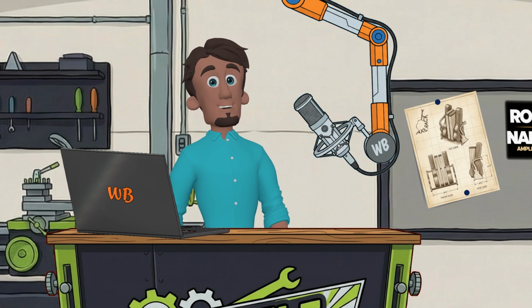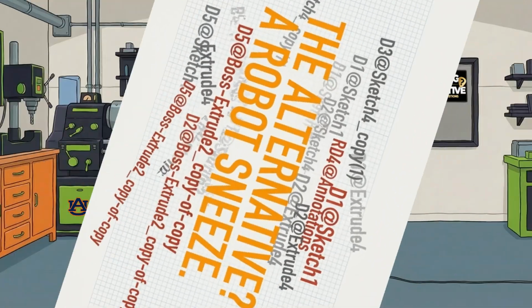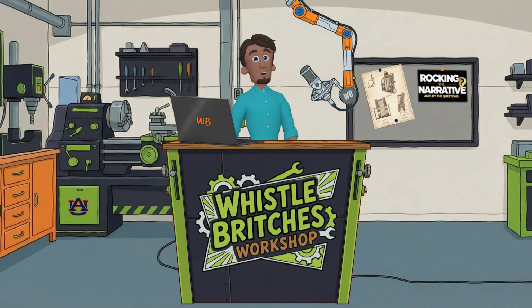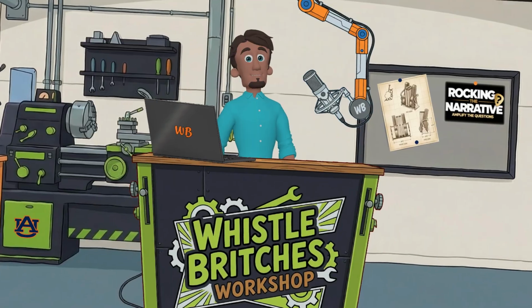Now this is a really simple example, but on a larger project, if you don't do the prep work and rename your features and dimensions to something you'll easily recognize, your captured dimensions and features list will look like robot sneeze instead of English. Now, there is another way to name those captured features and dimensions, and you may have eyeballed it already. I'll show you that when we capture a feature or two in the next lesson.